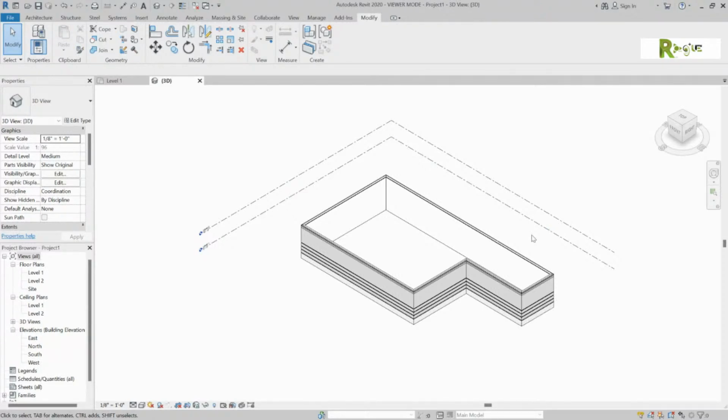If you go down to the lower left-hand corner of the screen, it says 1/8 of an inch. I want to show you where the shaded view is. That's the second icon past the 1/8 inch, the little box. Hit that and do shaded.